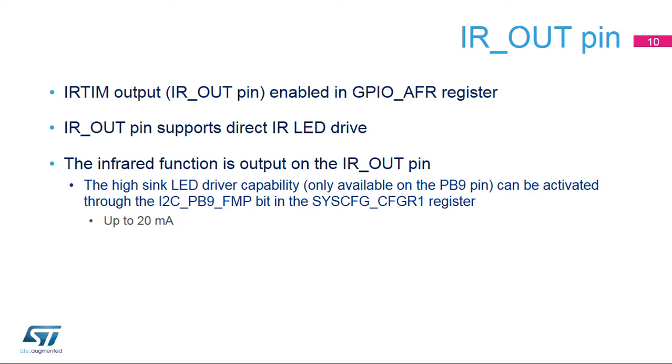The IR output pin can directly drive the infrared LED, especially on pin PB9, where the high sink driver capability is supported. This feature can be activated through the system configuration register. GPIO PA13 doesn't support this option.